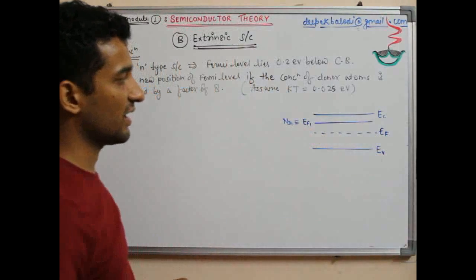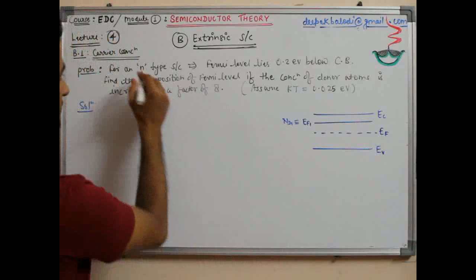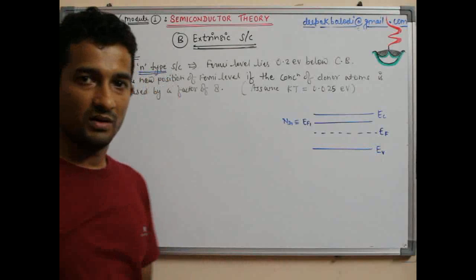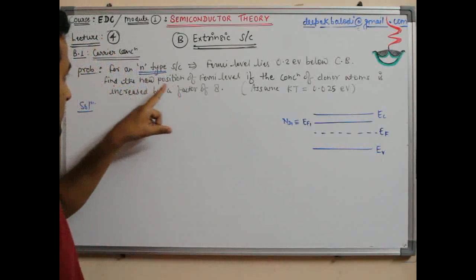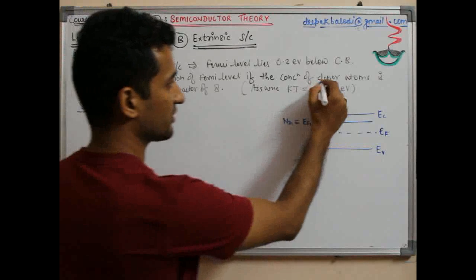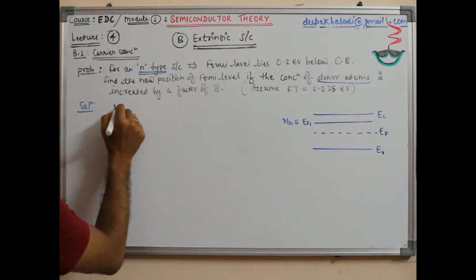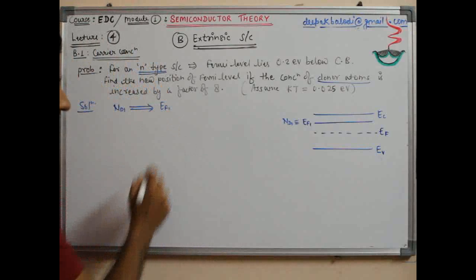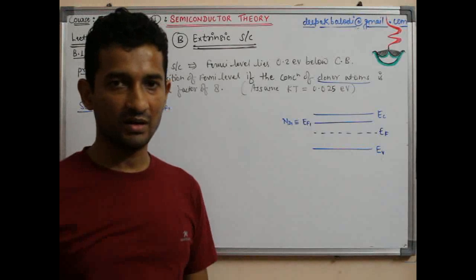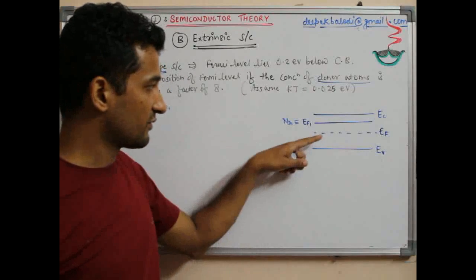That means when we have done a doping of ND, because this is n-type. N-type is a result of donor impurity concentration. That's what is confirmed with the second line, donor atoms. So with the ND1 concentration, let's say it corresponds to EF1, and definitely we know that for n-type material with donor impurity concentration, the Fermi level goes up from EFI.